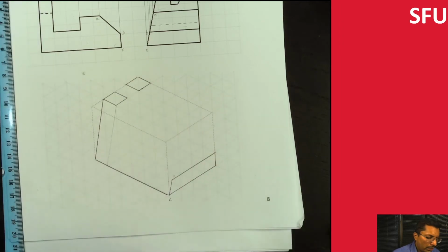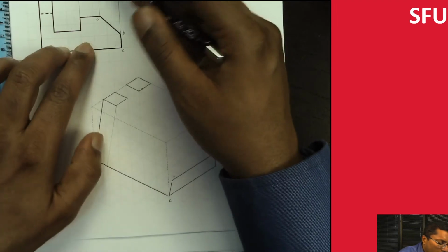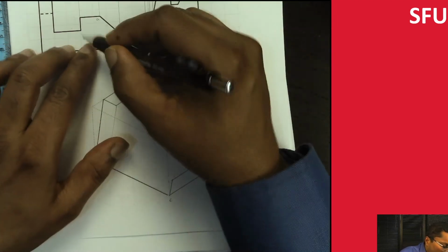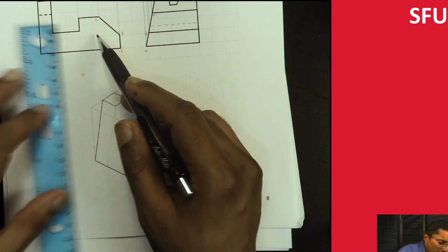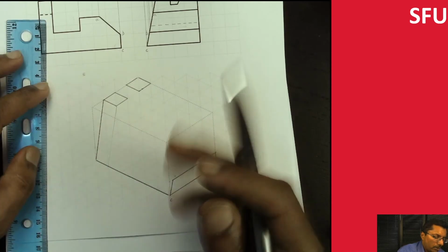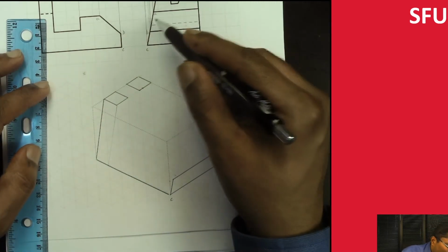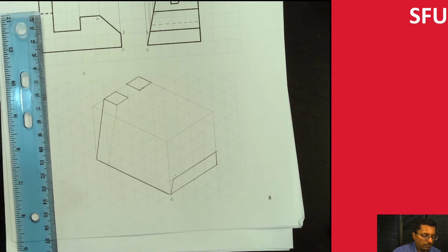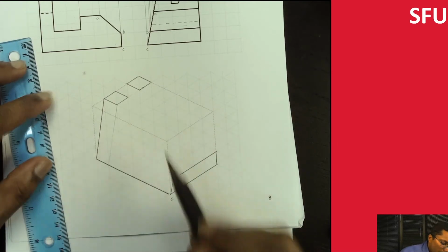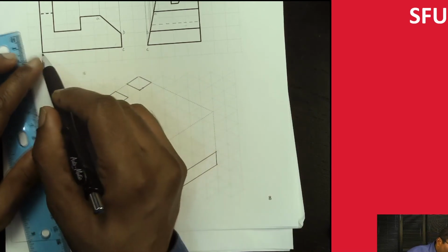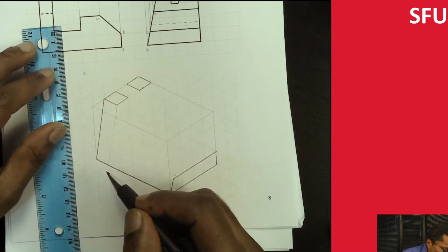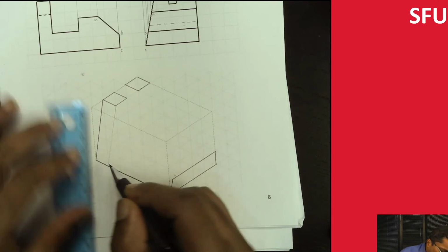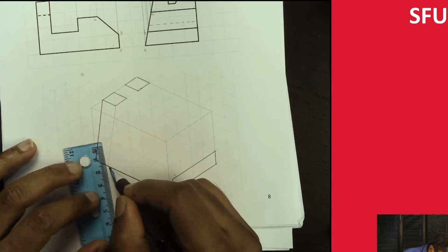So let's start looking at more challenging parts. The flat ones are always a little bit easier, so we can look at this part. Let's see, this part, where is it located? So this, I can once again use the compass, or I can use essentially the ruler to get the dimension. To get to this point, I need to go 10 millimeters from the back. Then I'm going to go 15 millimeters up here.